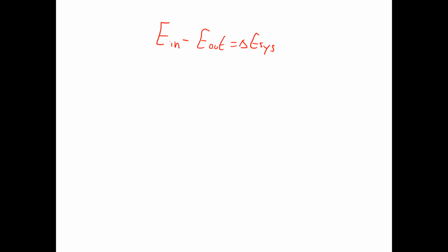Now what we're doing is a first law analysis on the balls as they are rolling. So I don't have any energy by mass entering the balls, nor by heat, nor by work. The moment they enter the oven, they're actually losing heat to the environment. So the only energy exchange going on is heat leaving the ball bearings. And the change in energy of the system is equated to the change in internal energy, plus the change in potential energy, plus the change in kinetic energy.